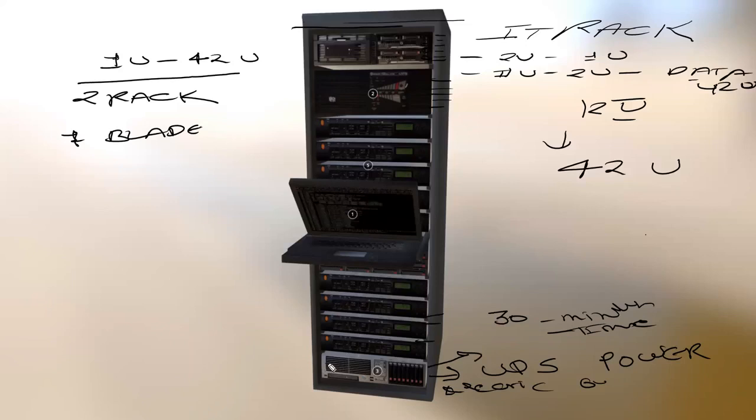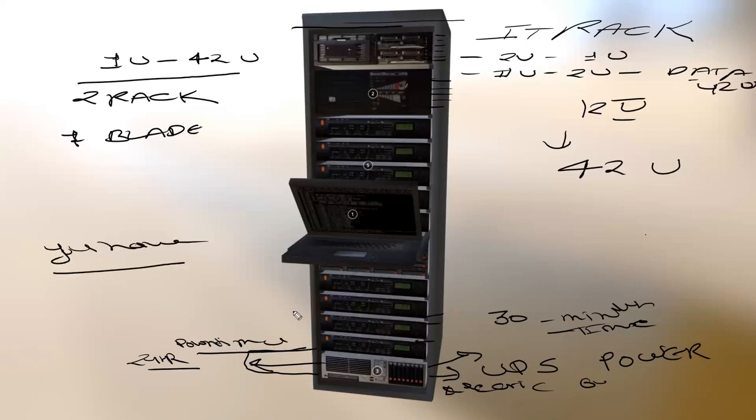So it's a very important part. You must have this at your location. And why do you need it? Even if you have 24-hour electricity, you cannot rely on it, because someday you could have downtime due to repair or maintenance in your building, and they may ask you to do a shutdown. You may have critical customers who don't want any downtime. So you need to make sure that your UPS is compatible with the power given to you, and that the server can run for at least 30 minutes or the time of maintenance. So you must make sure.